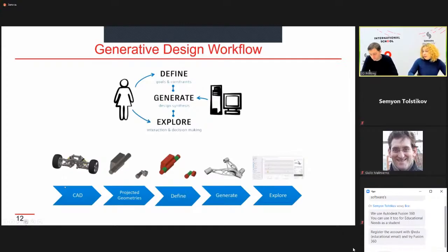What about the analysis? We analyze some stress, some mechanical properties, and try to find better solutions for our goals. And we think about manufacturing technology. If we use 3D printing, I think you remember what it means, additive design. I hope you remember. It's the part position, part location on the building platform or substrate of the 3D printer. It's adding some support materials in order to support the overhang surface of our product. It's the set of technological parameters for printing, which is connected with our material, the properties of our material.